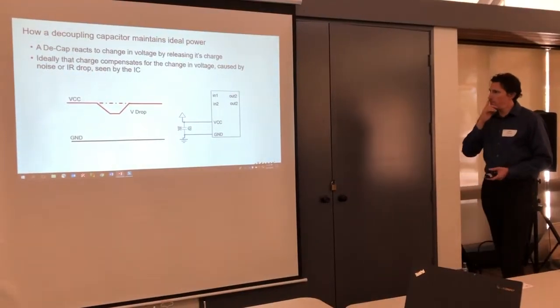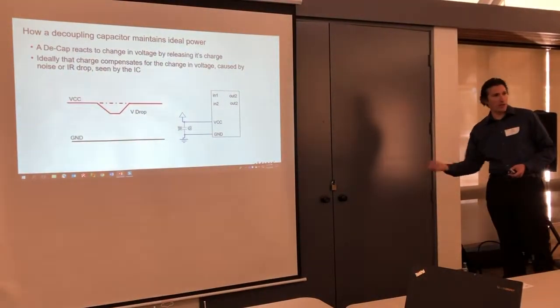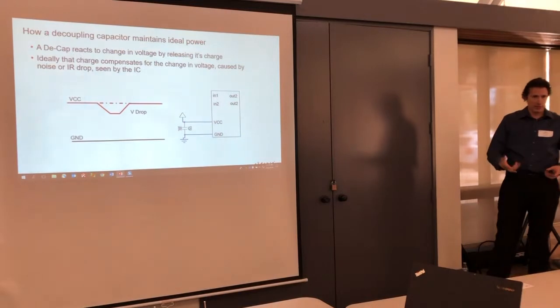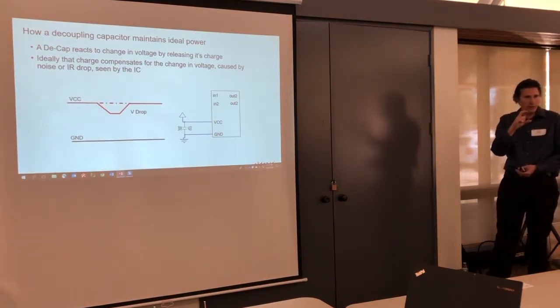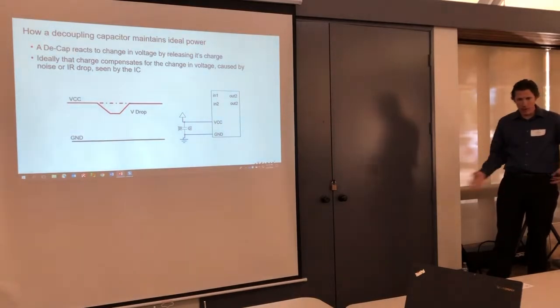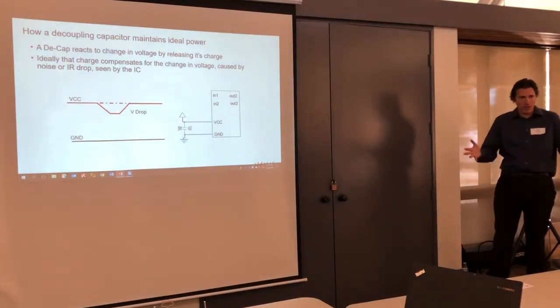And so that's why you always have all these decoupling capacitors all over your board. The idea of the decoupling capacitor is to recognize that drop in the power next to the IC, because the decoupling capacitor is basically storing charge, right? When the device powers on, the power goes through the capacitor, it fills up on charge, then it kind of acts like it's not there.